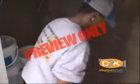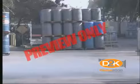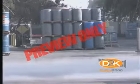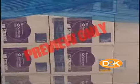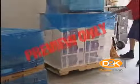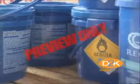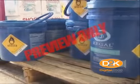1. Store chemicals properly in a cool, dry, well-ventilated area. Heat or water reacting with a chemical can cause fumes or flames. Proper ventilation of a storage area is important to reduce any buildup of fumes. It's best to store pool or spa chemicals in an area dedicated solely to them. Many pool or spa chemicals are corrosive to metals and should not be stored in the same room with metal equipment, such as a pump or utility room.